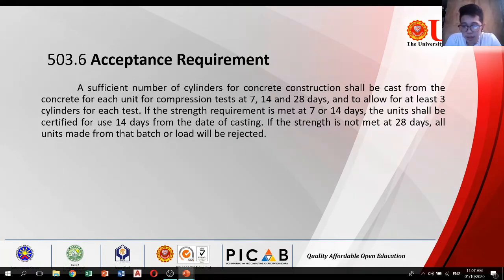So the steel grating plants will be inspected periodically for compliance with specified manufacturing and fabricating methods, and bar samples will be obtained for laboratory testing for compliance with material quality requirements. So all drainage grate materials shall be subjected to inspection for acceptance at the latest practicable time, so the engineer has the opportunity to check for compliance prior to or during incorporation of materials into the work.